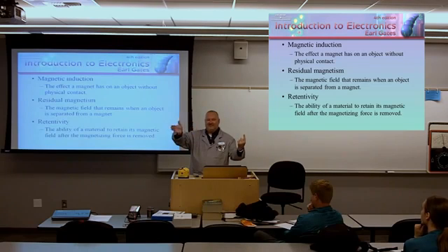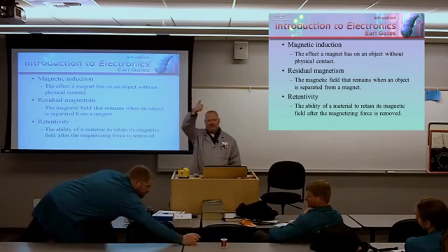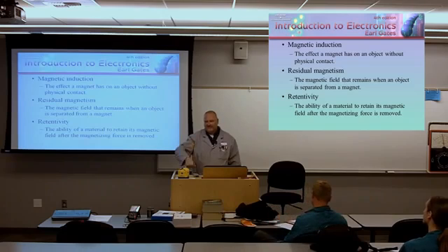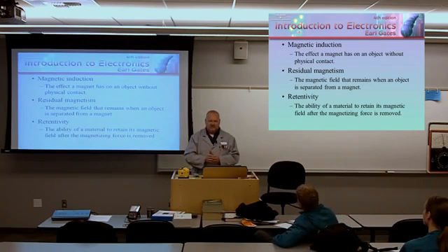Then he'll shut the radar off, and then he'll drive his cursor over to where he had that contact and hit enter. Autopilot will bring the airplane to that point in the ocean. And then the operator is looking at the MAD gear. And then all of a sudden they start to get a magnetic anomaly. At that point they pop a flare out over the target. If you're at war, at that point the aircraft is going to go into a bank, start to open the bomb bay doors, fly right over that point, put a torpedo in the water. It's a smart torpedo. It's going to find the target and blow it up. That's how you die in a submarine in a combat situation.